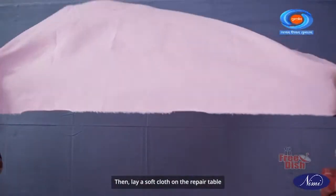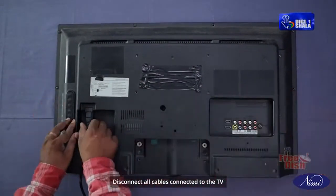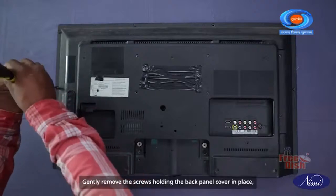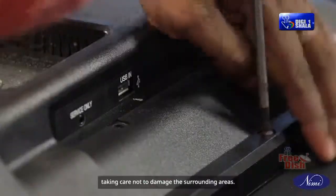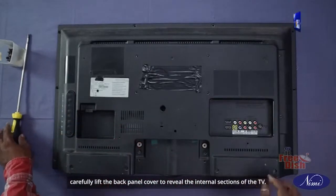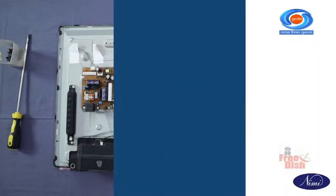Then, lay a soft cloth on the repair table to protect the TV's surface. Disconnect all cables connected to the TV to ensure safety and ease of access to its internal components. Gently remove the screws holding the back panel cover in place, taking care not to damage the surrounding areas. Once the screws are removed, carefully lift the back panel cover to reveal the internal sections of the TV. Take your time to avoid causing any unnecessary stress to the components.